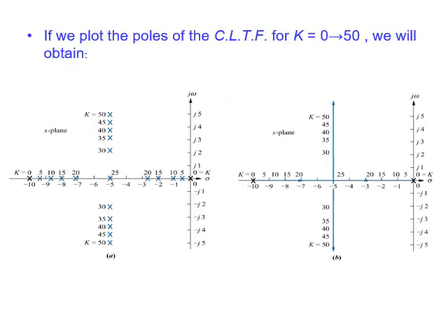So here are the changes. Assume the gain equals 0, the pole location will be as you see here. If the gain changes to 5, the pole location will be at this point, and so on. If the gain is 10, the pole location will be here and here. If the gain is 15, the pole location will be at -8 and -2, and so on. We reach a point, with a gain of 25, where the two poles come to the same location.